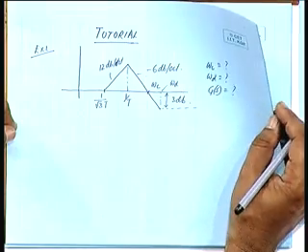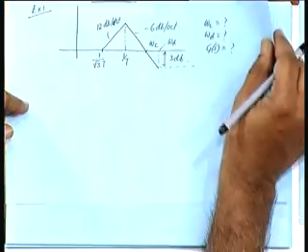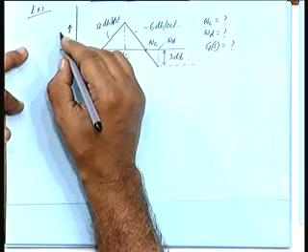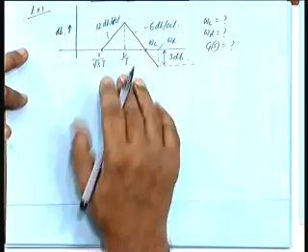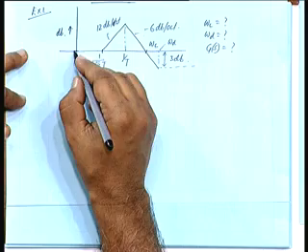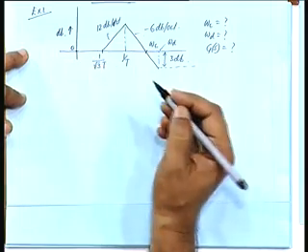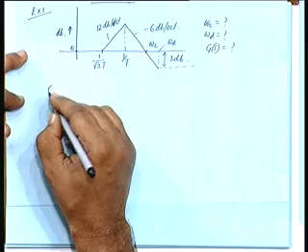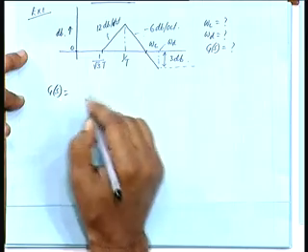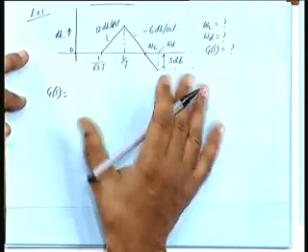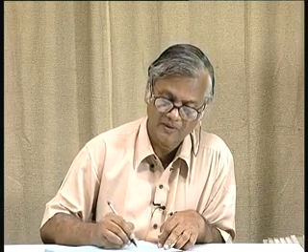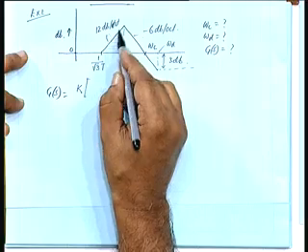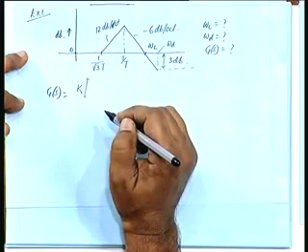Omega c is how much, omega d is how much, and then determine Gs. Okay. So, for this problem, this is the dB gain, this is the 0 dB line. So, could you suggest the function like Gs, what it would be like? Gs will be some constant times, it is a slope going up at this frequency.